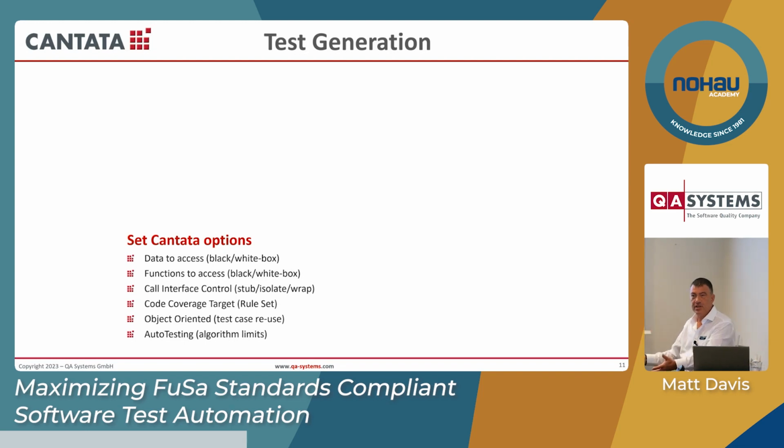I'm doing an ASIL B system in 26.2. I need to do 100% statement coverage. Not decision coverage, which is ASIL C, or MCDC coverage, which is all of the combinations of condition outcomes for ASIL D.